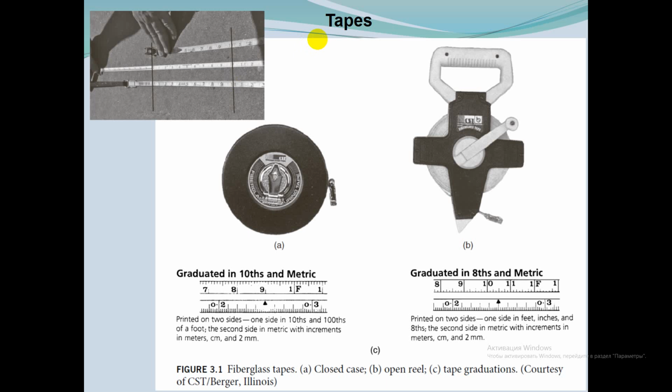Measurements taken near an electric station should be made with dry, non-metallic or fiberglass tapes. Fiberglass tapes have now come into widespread use.